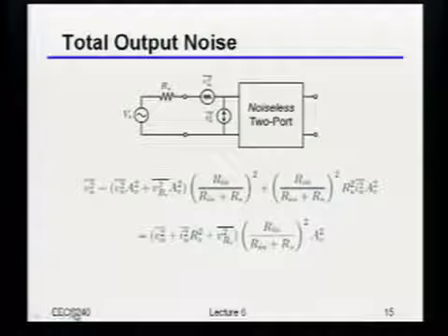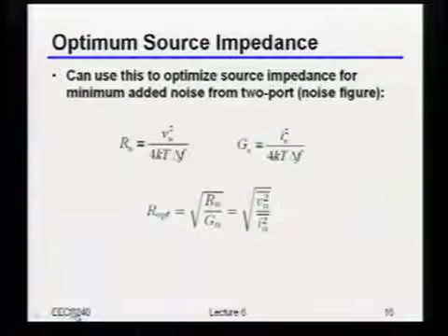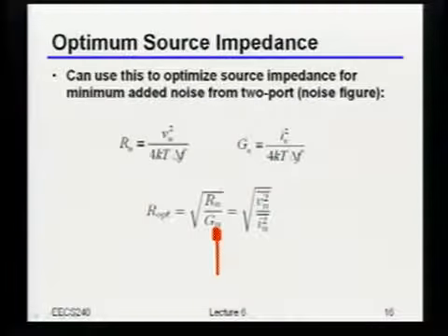So obviously you can take a look at the total noise you'd get as a function of the source resistance. That's nothing too interesting other than it gets you to this formula, this rule of thumb: if you know what the voltage and current noise generators are, and you could pick the source impedance, perhaps by doing some impedance transformation, then the optimum source impedance is just the ratio of the voltage to the current noise. Intuitively that makes sense, because that's what balances out those two contributions.